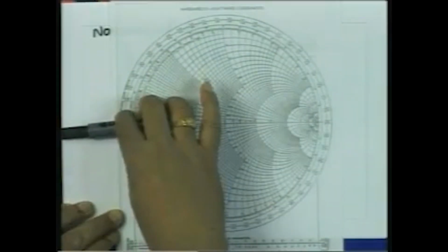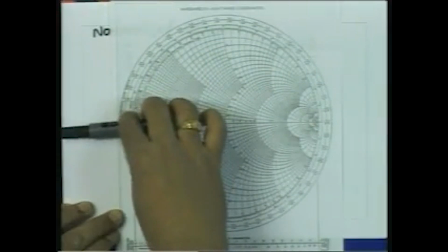Normally, whenever we do the Smith chart calculations, we do not rotate the Smith chart. We follow this convention that the Smith chart is fixed, but for impedance the gamma axis is like that, whereas when I go to the admittances I get the gamma axis which will be like this. So, depending upon whether we are doing calculation for the impedances or admittances, and if I require the phase angle measurement in the complex gamma plane, then appropriately the axis has to be rotated by 180 degrees depending upon whether I am using the impedance or admittance.